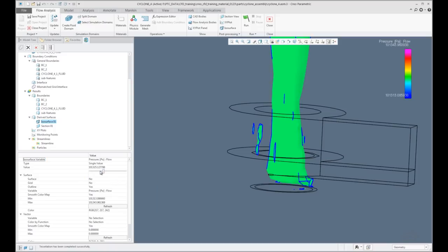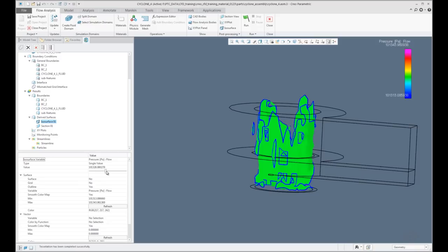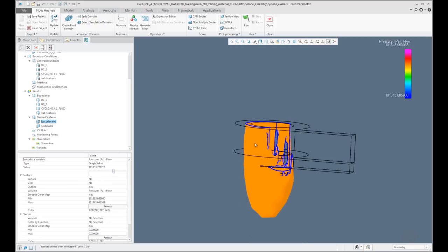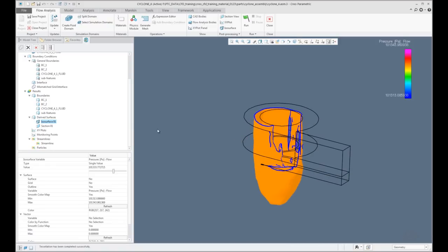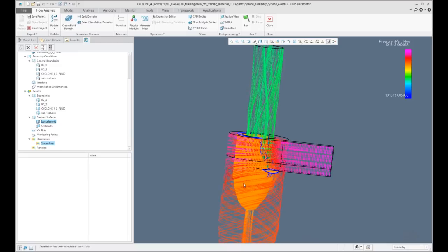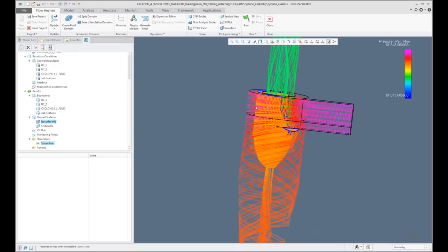and go and change the values now, so we can go and examine areas in the assembly here that have the same pressure within them. And again, if I go and turn on the streamlines at the same time, this gives us a better idea to look at the swirl of how the material is coming in, and then it's starting to feed down this vortex here.